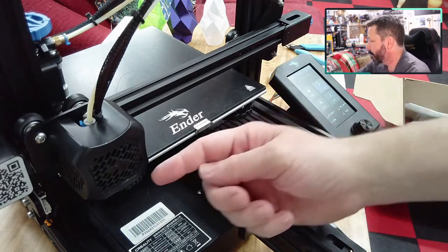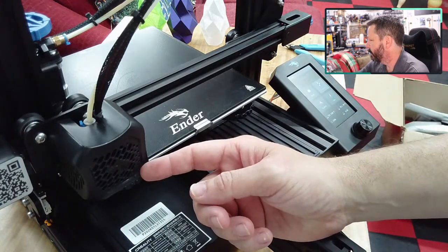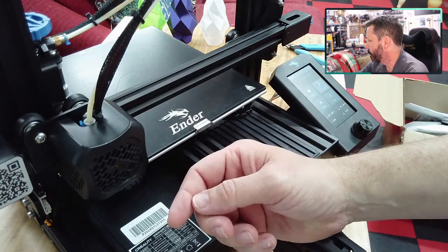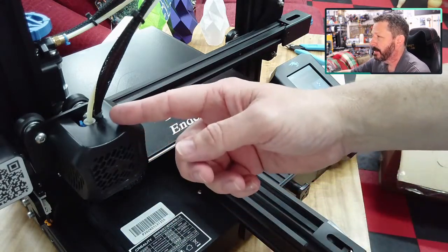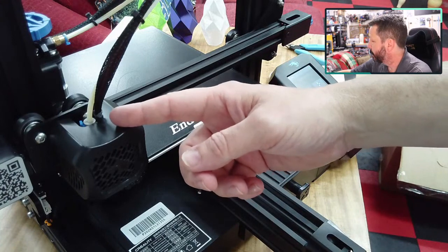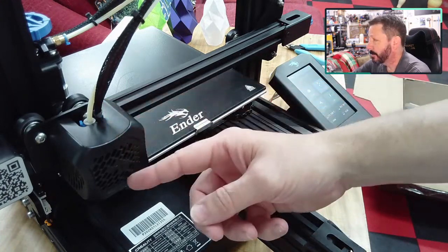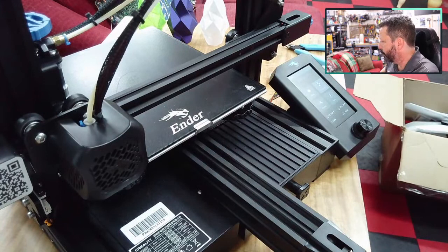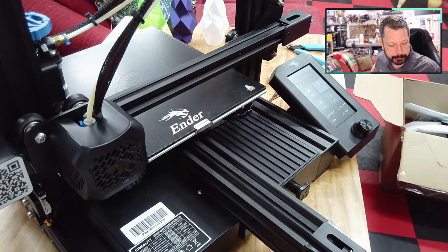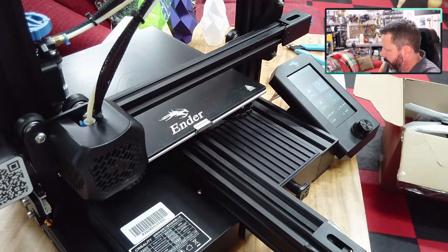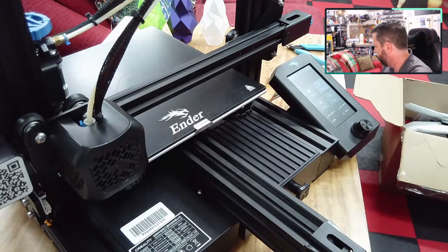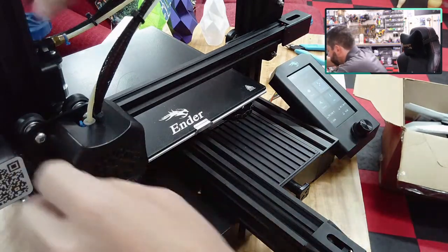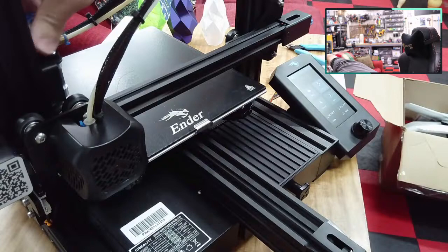Sometimes it's just a matter that it was clogged for whatever reason, and we can just force that filament. Or sometimes it'll retract filament, depending on what the last thing you did was, and maybe the filament just hasn't reached the nozzle yet. So we're going to manually make sure that we can purge the filament out, and then we'll restart the print. I suspect the actual problem is the nozzle was too close to the bed and there was no room for the filament to come out. Alright, so let's see if we can get filament to extrude now.